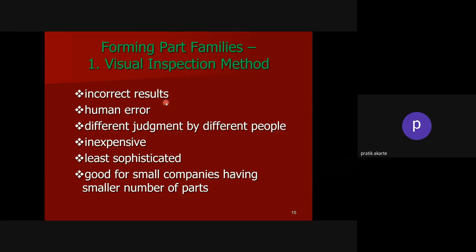it requires a considerable amount of experience to group the parts into part families. If you look at some parts, overall they may look similar, but if you go for the entire processing of the part, it may take different routes for different parts. So, as I said earlier, it requires a considerable amount of experience to group the parts into part families just by visual inspection. And if someone is lacking this kind of experience, then it will lead to incorrect results.